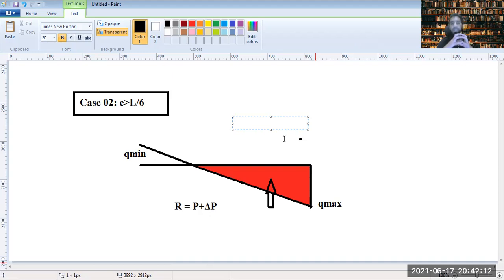If we make the joints rigid, and we're trying to arrive at a design which is actually economical, and if we can also eliminate the eccentricity by making the sections symmetrical. We can eliminate the eccentricity by making the sections such that the load is equally distributed within the sections. So our focus should be to eliminate eccentricity.